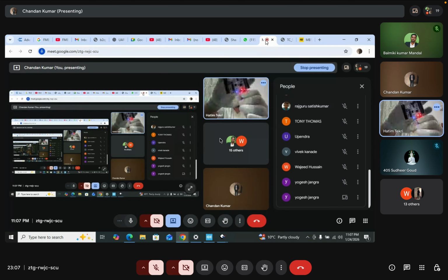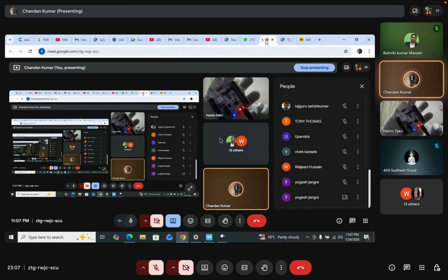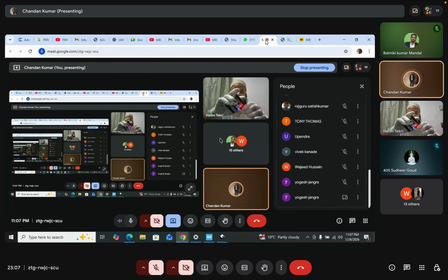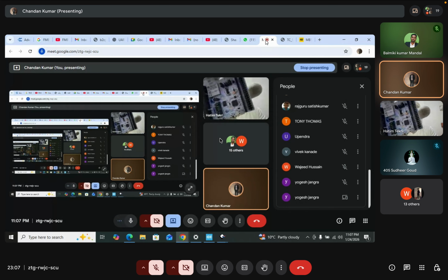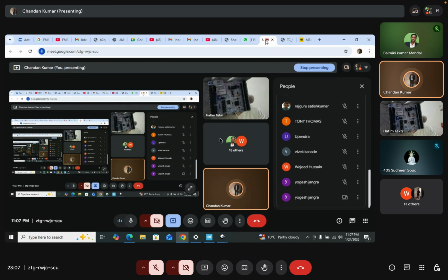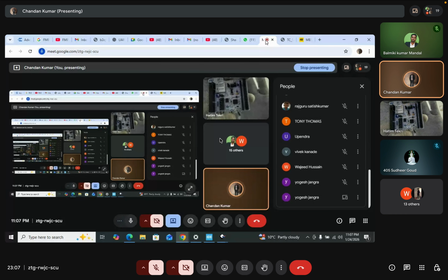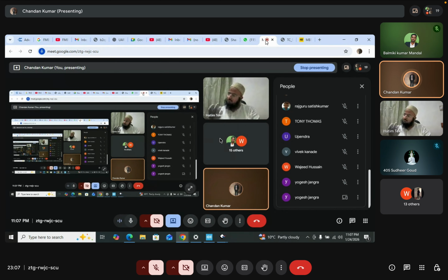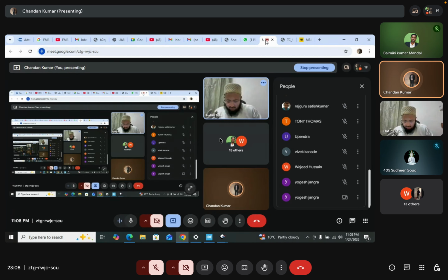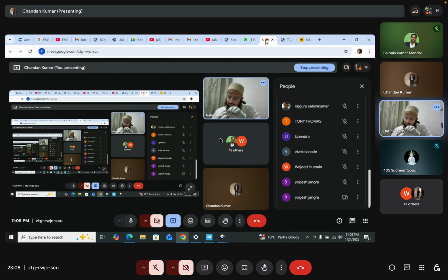Here is the CN10. Remove this USB cable because static current will be there. Okay, so if you watch your controller carefully, you will find names written like CN8, CN9, CN10. So just find CN10, that's available on the right side. And Hatim, can you connect those two pins, RX and TX? Pin number 34 and pin number 6. CN10 34. Yes.